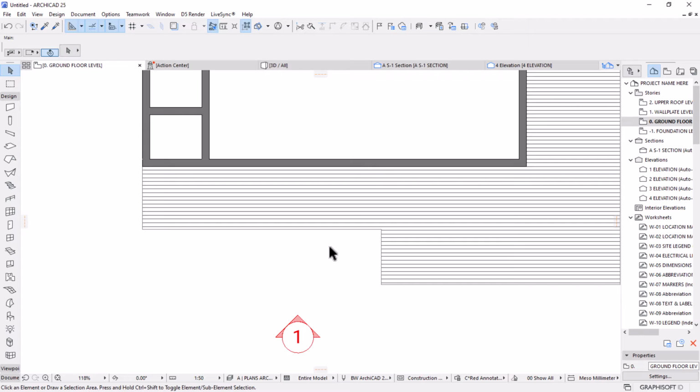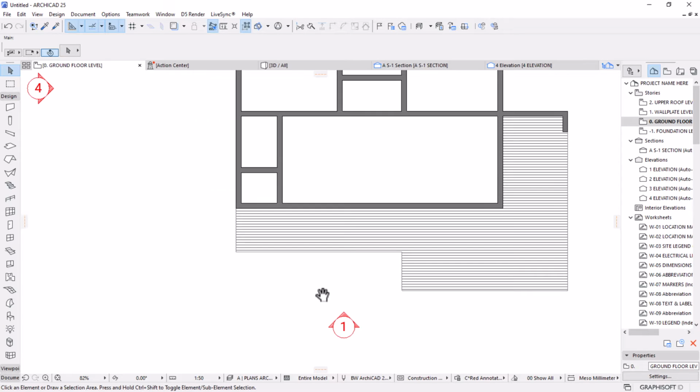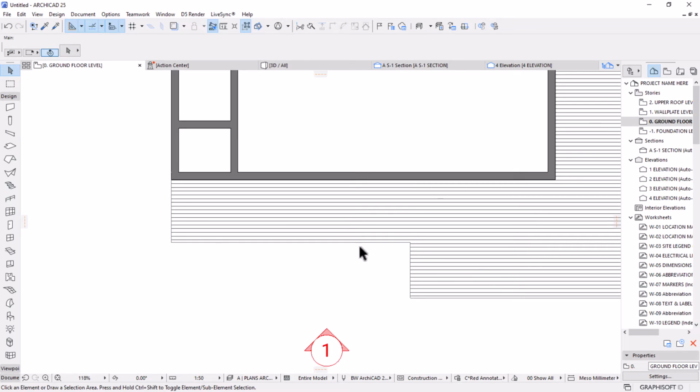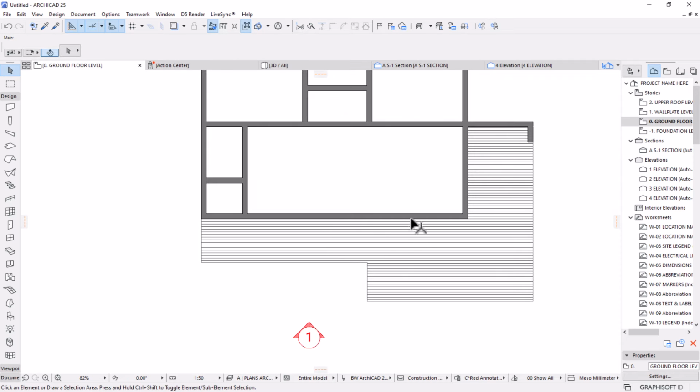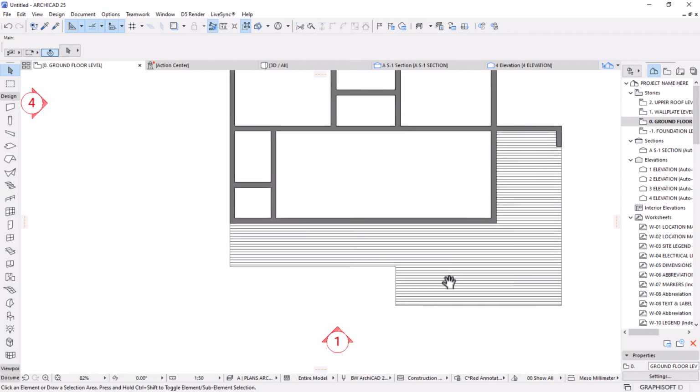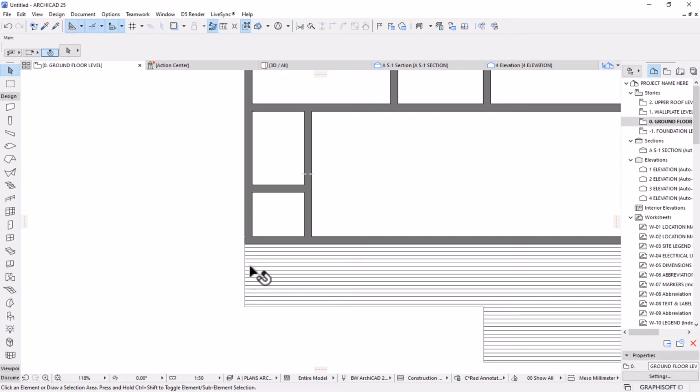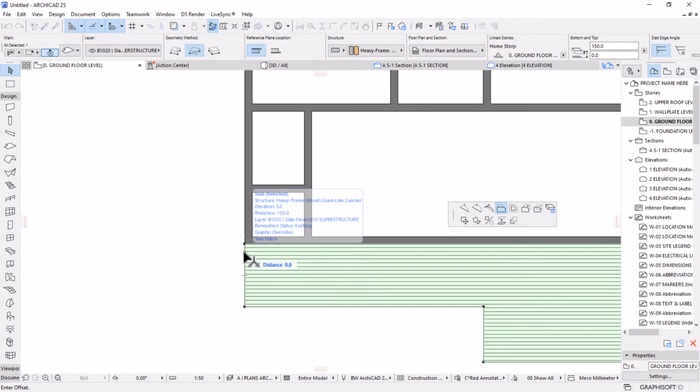And we're going to have again the staircase here. I think 4 steps of staircase, because this is a deck, guys. It's a suspended floor. So I would start by placing those staircase access. Again, we have another part where this deck has to wrap around to access this toilet. So I'm going to select this and then pick the edge, offset the edge by, let's go, 800.